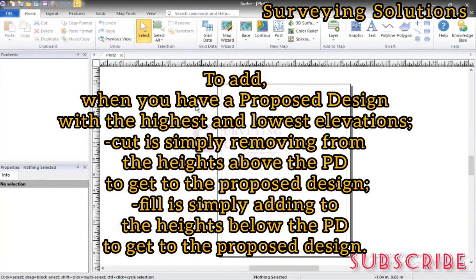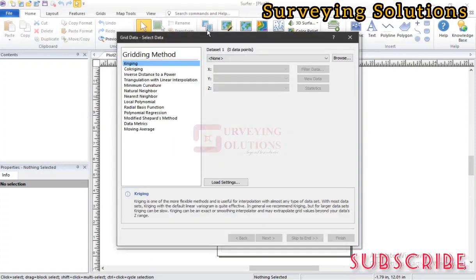So now we have our software here, and we want to bring in grid data, right? So you come to grid data. We are actually using the conventional gridding. We would have used triangulation with linear interpolation, but let's use the conventional grid. So you go to browse.